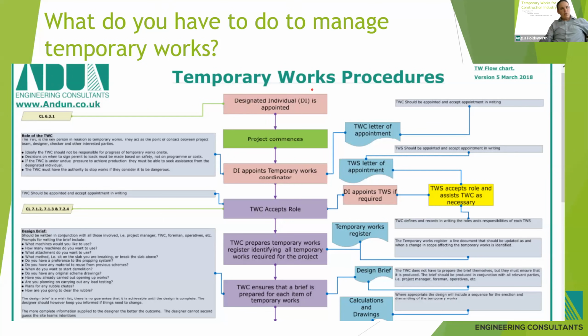So every organisation should have a DI, a designated individual. They are the person in the firing line, shall we say, in regards to temporary works. So they are the person who says whether someone's competent to be a TWC or to be a designer.